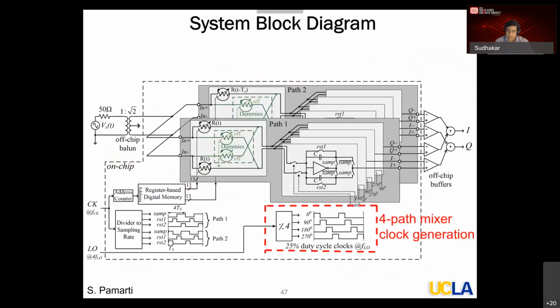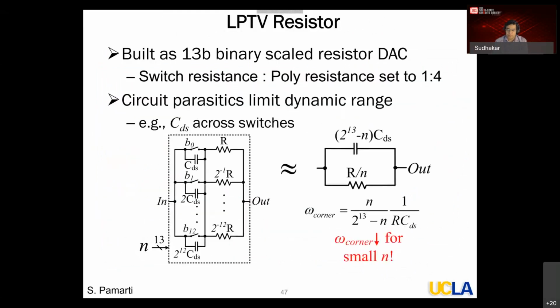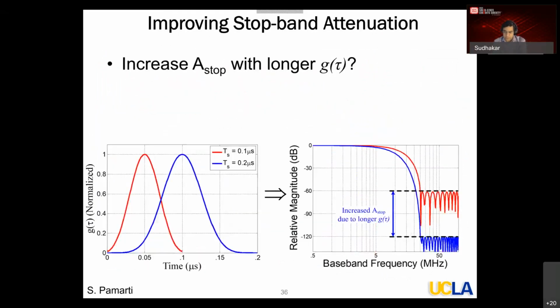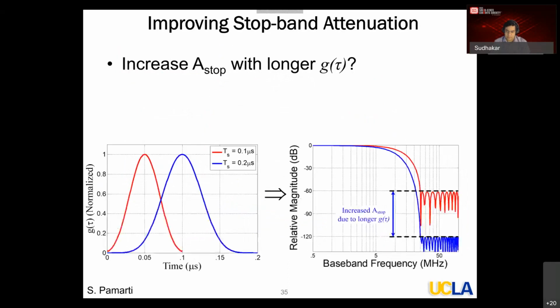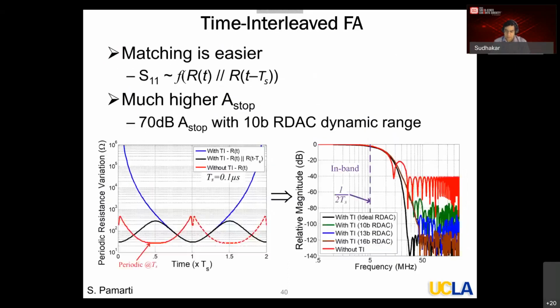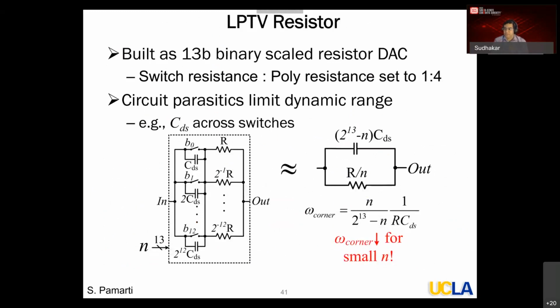Having said that, let me mention one other thing. I think I went a little too far back. So this green curve is a 10-bit DAC, right? I'm quantizing my coefficients to the resistance values to 10-bit. So if the resistance has errors below the 10-bit level, you will still get the green curve. Having said that, a bigger issue is the capacitors and other parasitics.